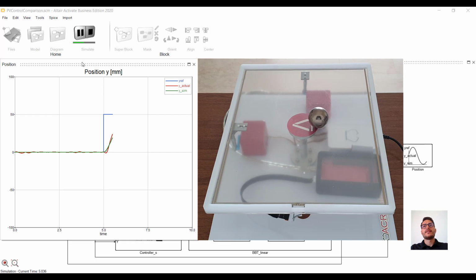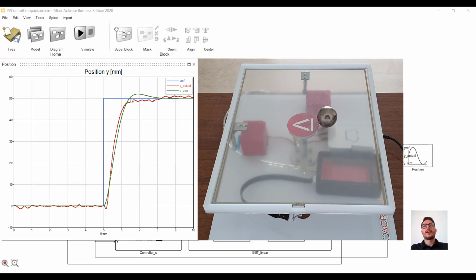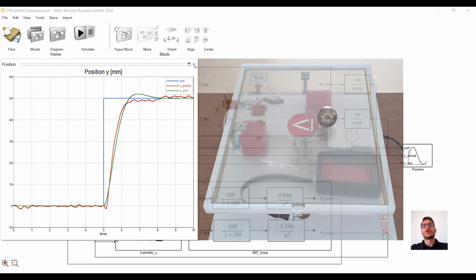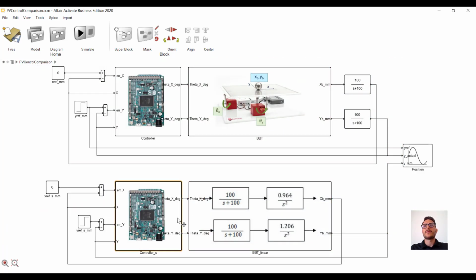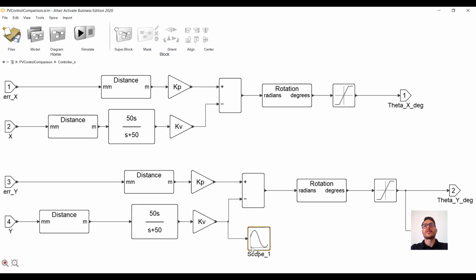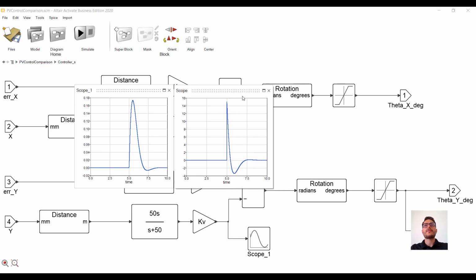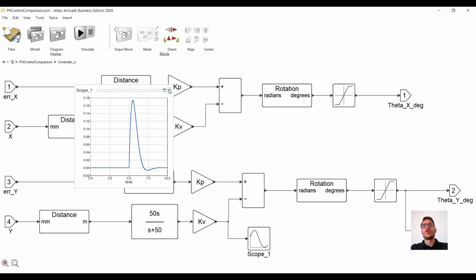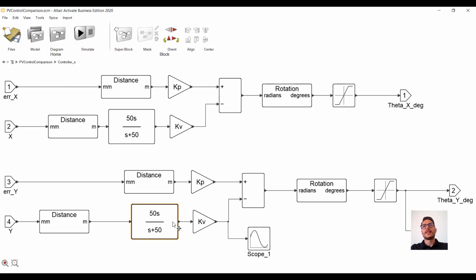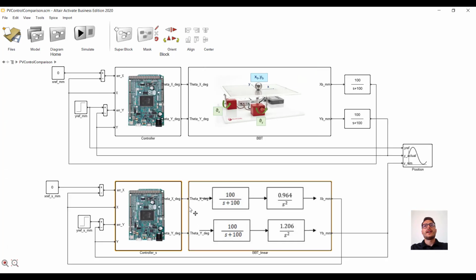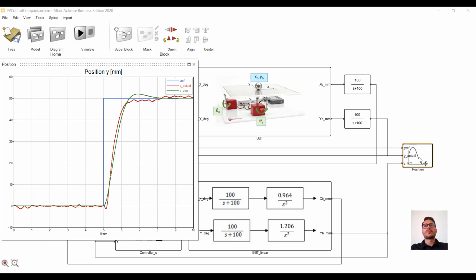We can see that the real system response is pretty similar to the PD control one, just a little bit slower, and it does not exhibit overshooting. Also this time, the linear model shows an overshooting different than expected, but the reason is not the saturation. In fact, there's no derivative kick, and the controller does not saturate. The difference is due to the low-pass filter that wasn't considered in the design phase. As with the PD controller, if the calibration is performed correctly, the steady-state error should be roughly 0.